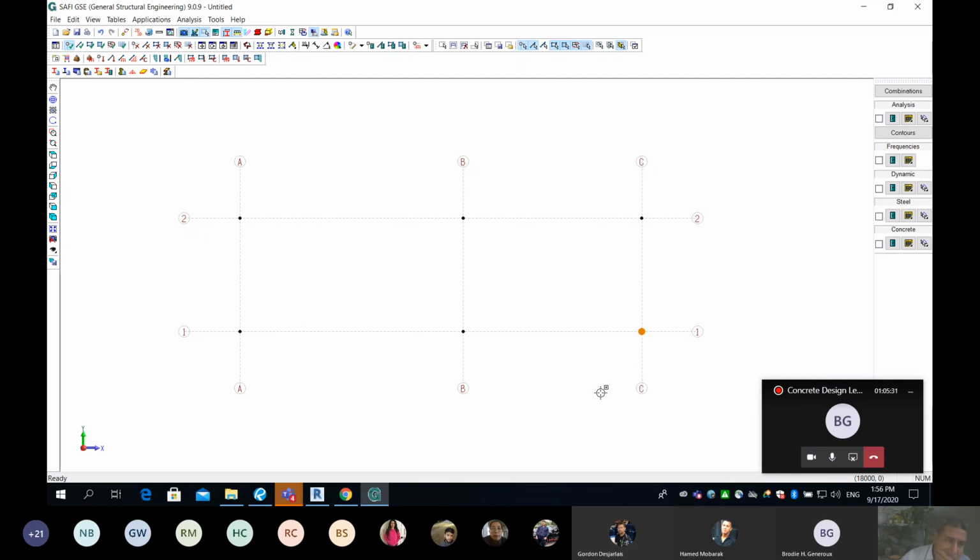Okay. So we go ahead and simply draw our members. I click here on Shift M or create member. And guys, you can see my cursor has changed. It looks like I'm ready right now to start connecting the joints and come up with the members. Watch me please, just like AutoCAD. You click here and then you go click here. It means I've done my first column. Now I go here, I go there, second column. I go here, I go there, third column. Now I'm missing the beams. So I go here and click there. So this is another one. And then from here to there, last one.